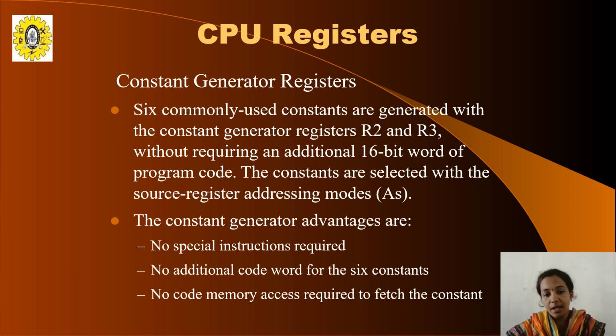So the constant generator advantages are that no special instructions are needed for the microcontroller, which would otherwise have to be given by the user. No additional code word for the 6 constants is needed. No code memory is separately needed to access the constants.